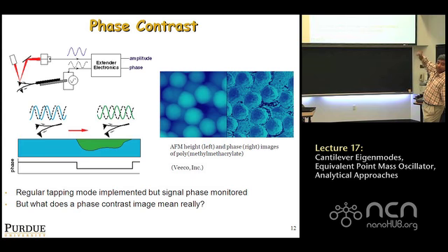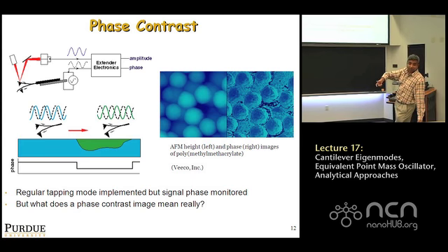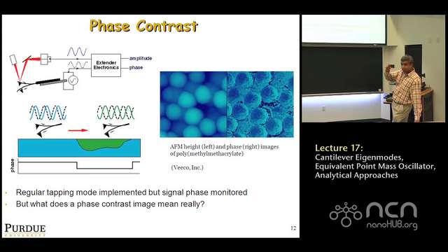That's the sine wave you're measuring, right? So you've got two sine waves. One sine wave goes in, the excitation, the dotted line. The output is the solid line, what you're measuring. There's a phase difference between the two, right? So there's a phase difference effectively between the shaking and the response of the tip that you observe.